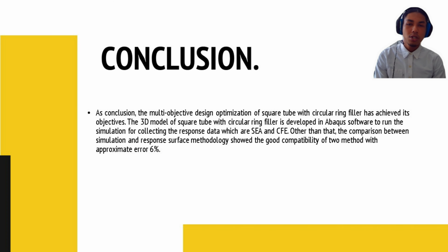Lastly, conclusion. As conclusion, the multi-objective design optimization of square tube with circular ring filler has achieved its objective. The 3D model of square tube with circular ring filler is developed in Abaqus software to run the simulation for collecting the response data, which is SEA and CFE. Other than that, the comparison between simulation and response surface methodology shows a good compatibility of the two methods with approximate error 6%.